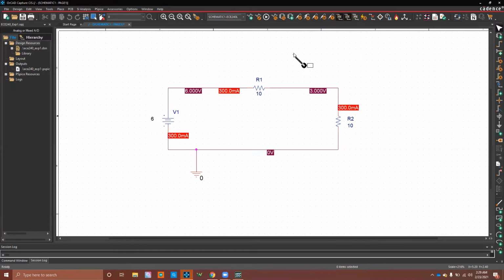This is like the probes on the multimeter. So when you first press that icon, the voltage differential markers, the first probe to come out is the positive one, or the red one. So when we have a circuit element placed horizontally, we typically go from left to right. And you can see they're named V plus, V minus.